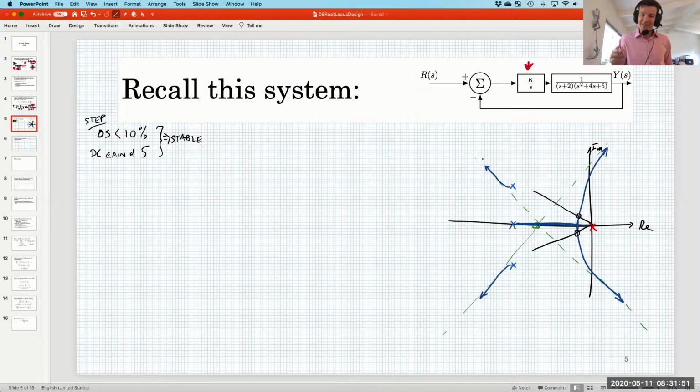The idea is, if there were no error, then a unit step in would produce a unit thing out. And we explicitly now don't want that. So I think by specifying the DC gain as not 1, we have said that in response to a step, we need error. That is part of our system design.